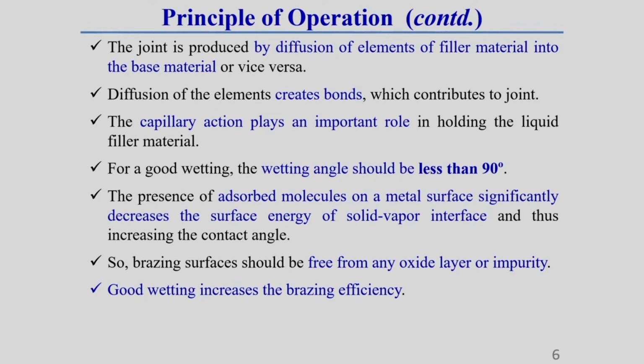So, this third point I have already discussed: capillary action plays an important role in holding the liquid filler wire. One thing you should keep in mind: whatever filler wire we use should have good wettability. For good wettability, its wetting angle should be less than 90 degrees.